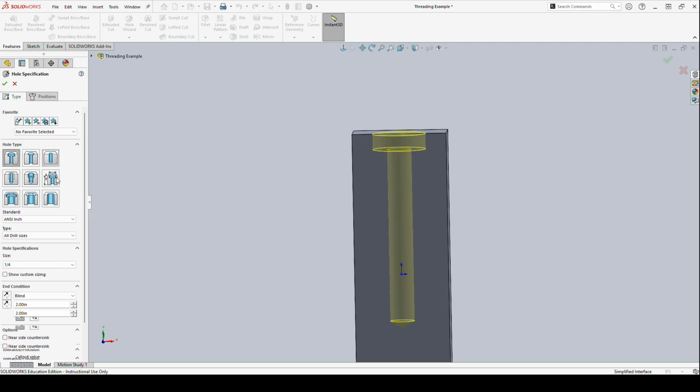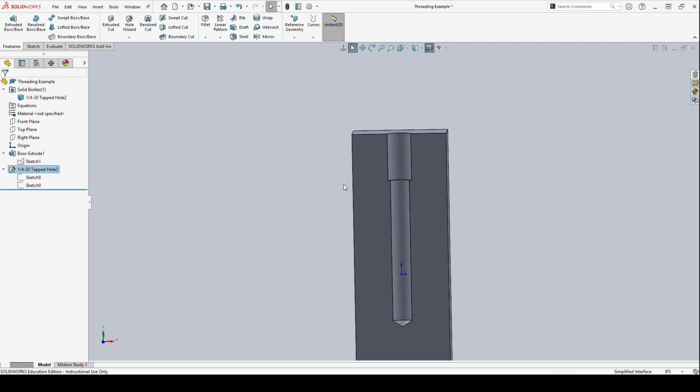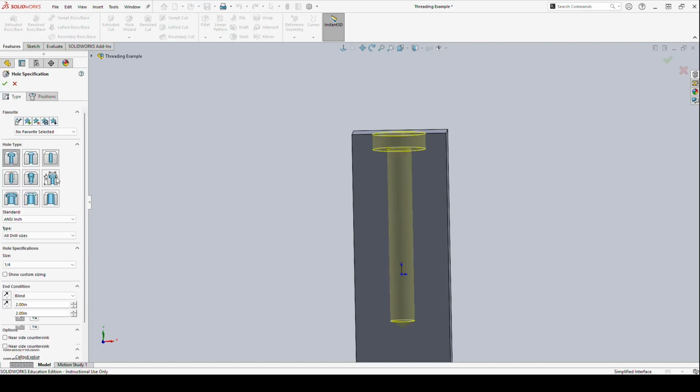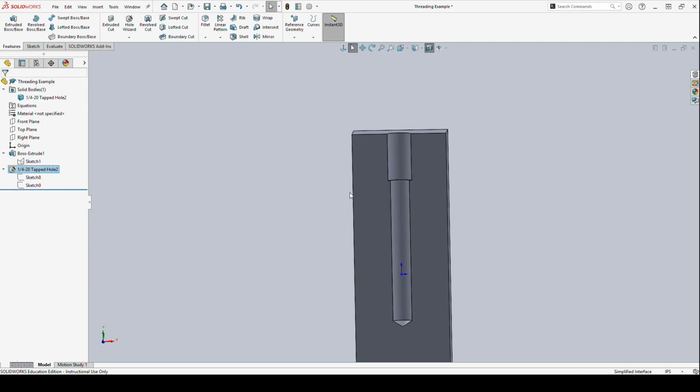Next piece we're going to talk about is our threaded holes. I jumped the gun a little bit there. Let me get back to, there we go. We've got our threaded holes. So what this is doing is we're actually noticing that some of this changed, because this is now defining based off our threading, not just our screw that's going in, but we can still customize a number of pieces within this. So this is our only option of these 9 options that is going to add threading.